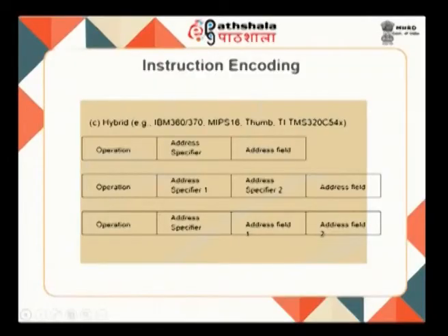that is a fixed format. Hybrid format tries to arrive at a compromise between the fixed format and the variable format, because the fixed format is very rigid, variable format is too flexible. You may have instructions which are of single bytes, you may have instructions which run to multiple bytes of length. So, you try to hit a compromise between the two and come up with a hybrid format, where you have only very few formats which are allowed, say 2 or 3 different formats, and all instructions will have to be fitted within this instruction format.